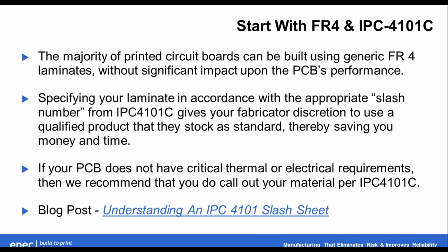So we're going to start with standard FR4, which is governed by the IPC spec number 4101C. The majority of boards can still be built using generic FR4 laminates without any significant negative impact on performance. We like to see you specify your laminate in accordance with the appropriate IPC slash sheet. The slash sheets are basically the different pages that describe the various materials, the properties, and the compositions. This gives us as the fabricator discretion to use a qualified product that we stock as standard, and therefore we can save you money and time.